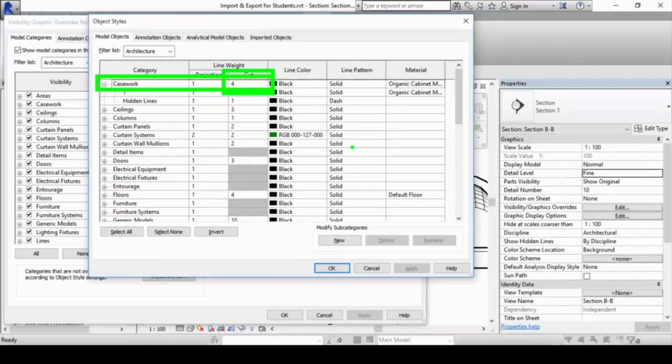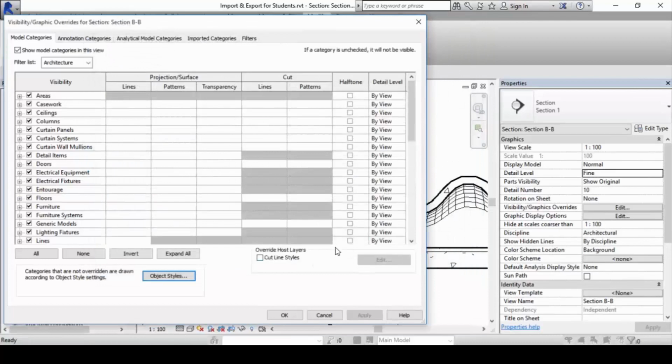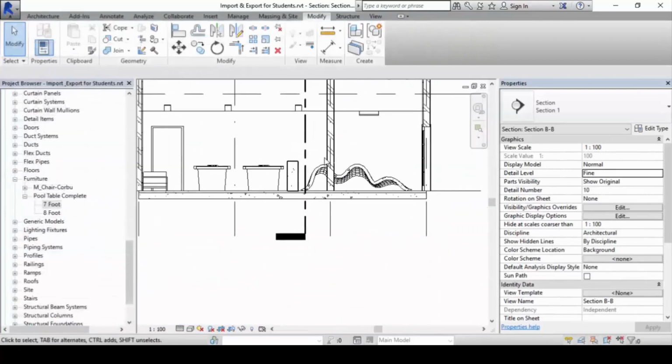So this is the limitation of Revit right up to now at this point. So foreign imported objects, yes, they can cut sections, but you will lose one category's line properties, line weight categories. So when you're doing this, if you have a few types, then perhaps you need to start putting them in different family types already. Okay, please take note of this.